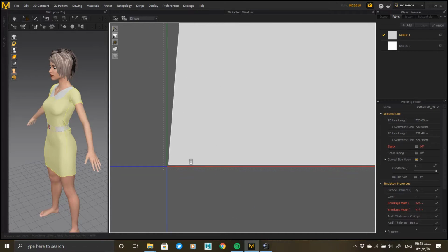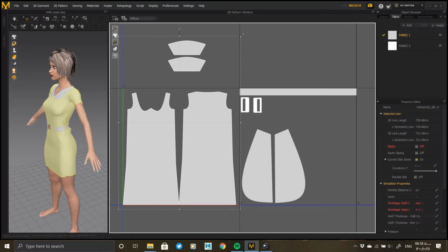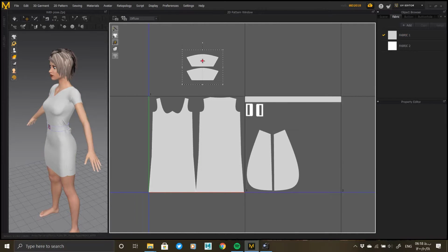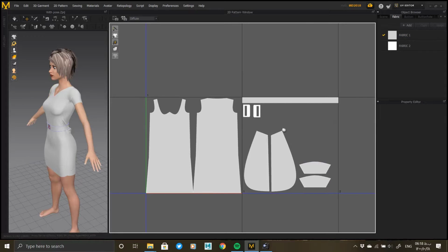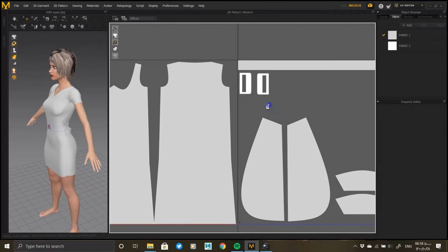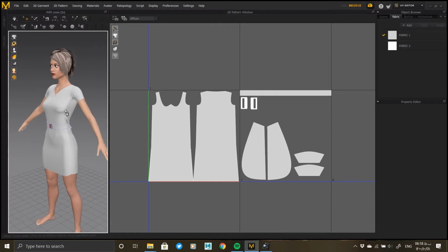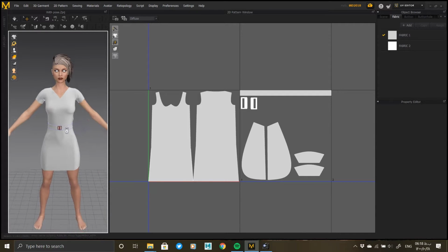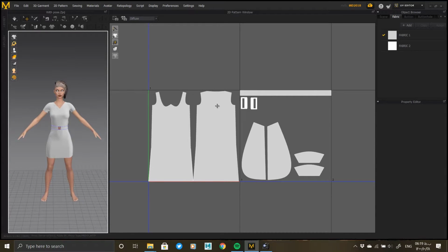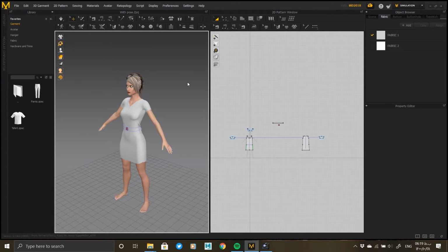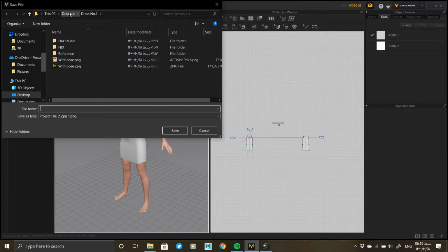In the next mode, you can select all and right-click on the model in the 3D window, to select the Remesh option. This tool regularly converts clusters into quadrilaterals, and is a good choice for people for whom the model topology is very important. But in this case, the corners and edges of each piece of fabric may not be quadrangular, in which case they can be adjusted manually, and finally, get a complete and excellent topology. After finishing the process, it is better to simulate again, and finally, the model is ready to output.